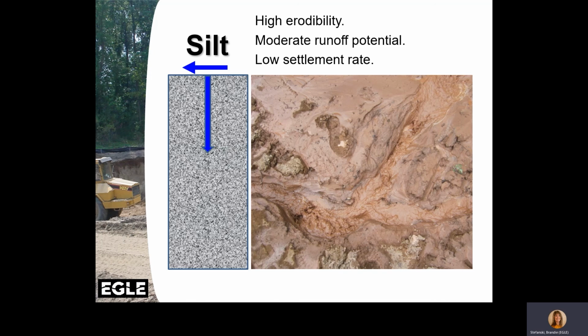Silt soils are easily eroded or highly erosive. They have a moderate potential for runoff because it isn't easy for the water to soak through the smaller particles. Once suspended in water, silt particles may flow quite a distance as they aren't heavy enough to fall out.